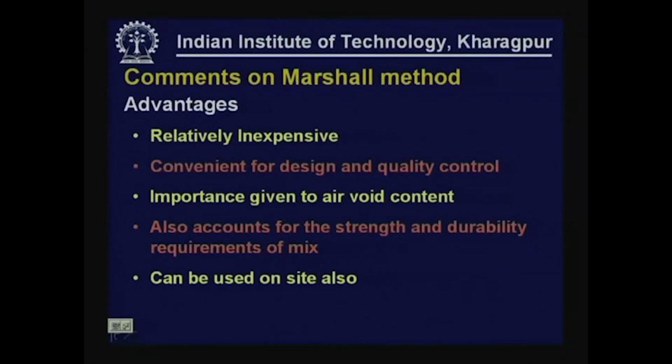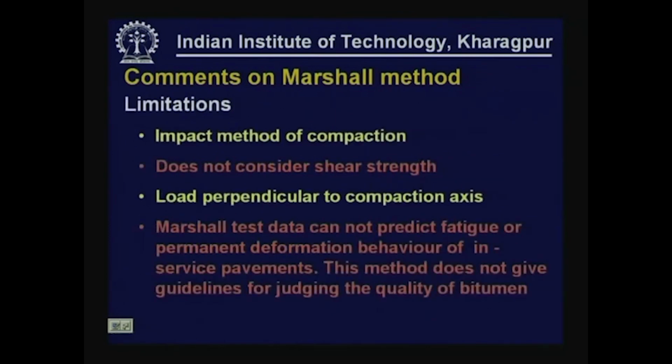A lot of importance is given to air void in this mix design method. As we already established earlier, air void content is a key parameter towards the performance of the pavements. It also accounts for the strength and durability requirements of the mix. It can be used on site also, but the limitations of this method are, this is an impact method of compaction. So, it does not really simulate what is happening in the field. There is some kneading action that is taking place. So, that is not exactly simulated in this impact method of compaction.